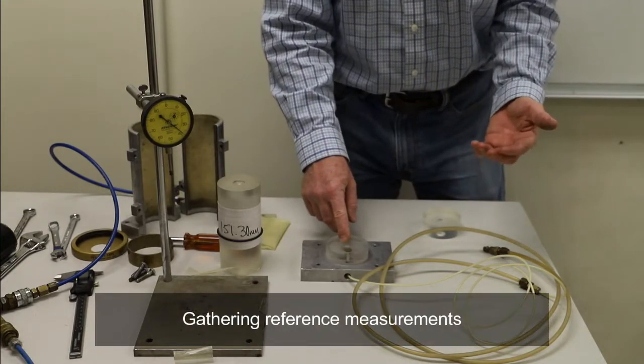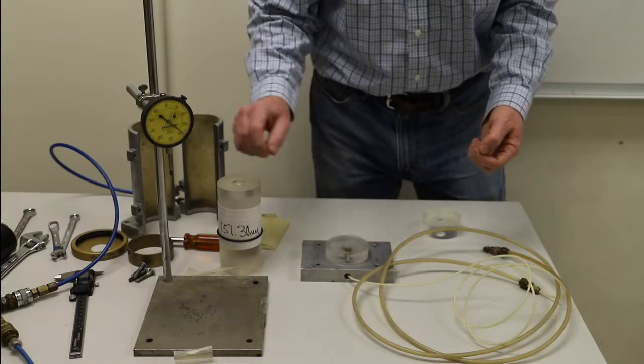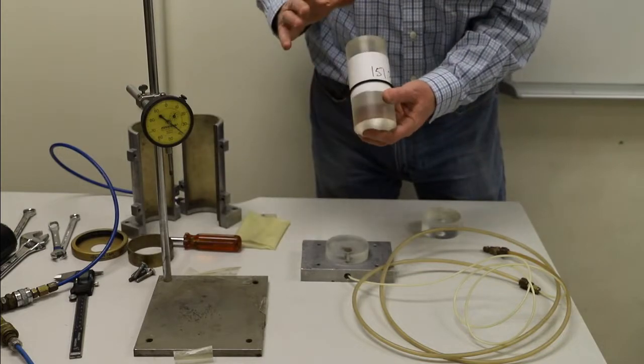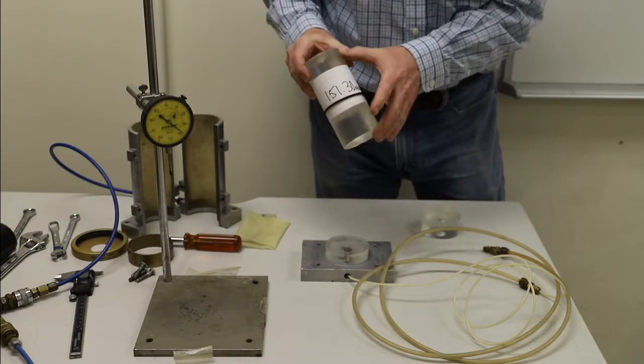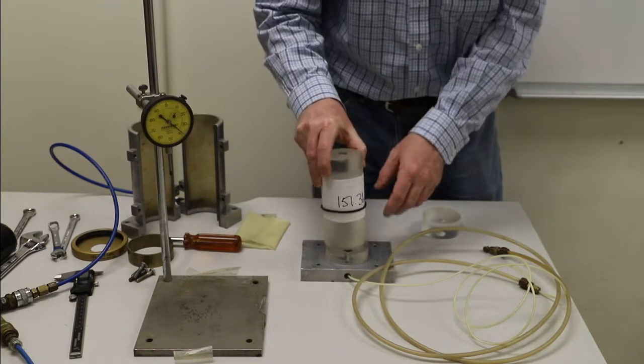Before we can build the specimen, it's a good idea to take some initial measurements. One of those is to use a reference height standard. So this lucite cylinder has a measured height of 151.30 millimeters.